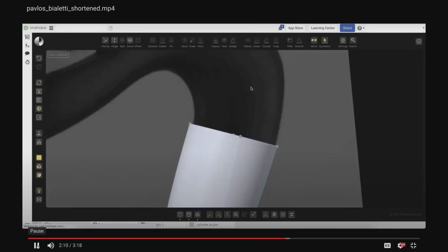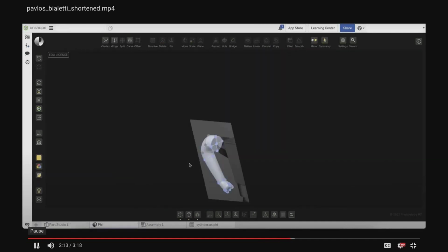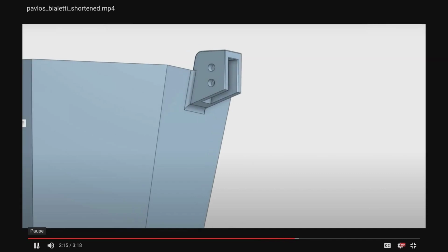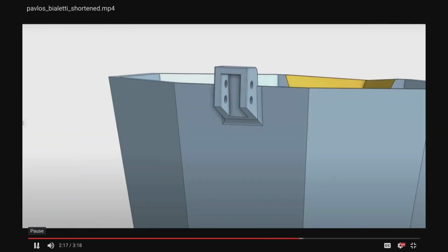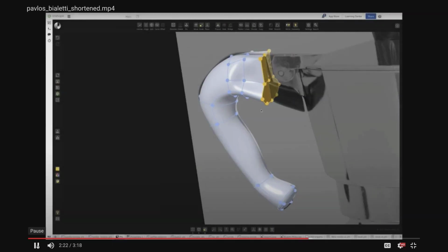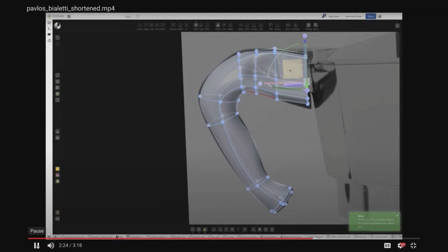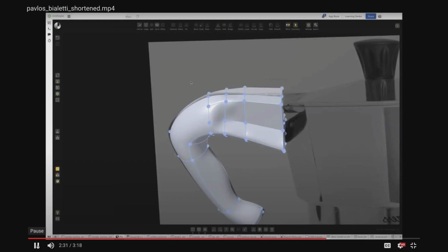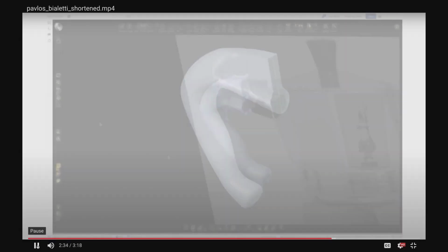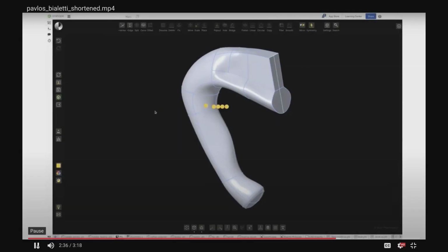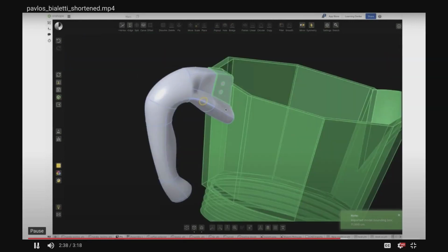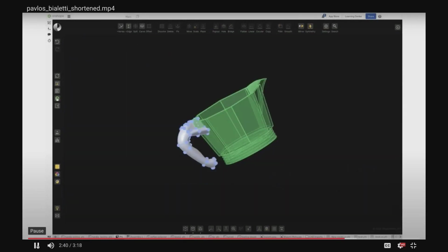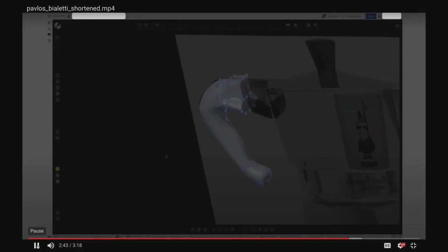So he completed this process moving upwards bit by bit until he reached the point where the handle is connected with the actual coffee maker container. So he examined the connection and he realized that he had to move from a freeform to a more rectilinear ending over there, which he easily did in FAI by adding some straight edges. And then he again brought in the reference model just to make sure that everything lines up correctly, and then sent his work from FAI over to Onshape.